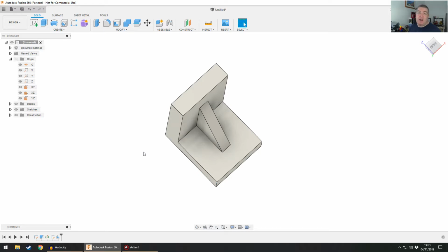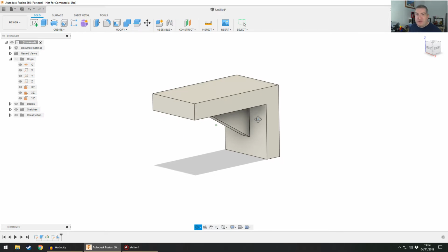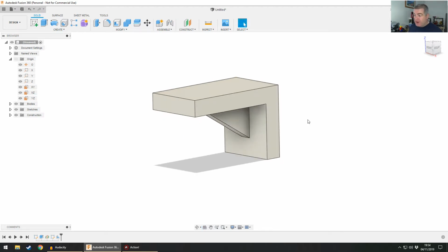So you can do design intent however you want, but design intent is pretty important. Like I say, it's not a hard and fast rule, but it is quite important to what you want to do. There's also something called the 80-20 rule. Now, you may have heard of this, you may not have. Quick time check there. The 80-20 rule means that on the model tree or the timeline down the bottom, 80% of your geometry, so 80% of everything that you see here, will be created within 20% of the features. The other 80% of the features are there to refine it.